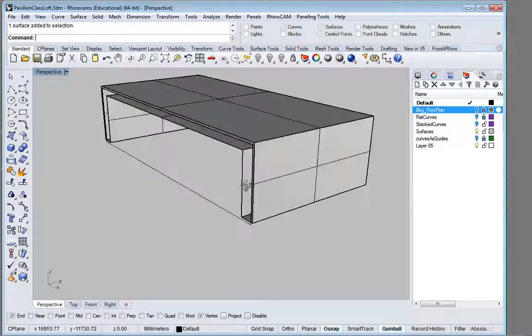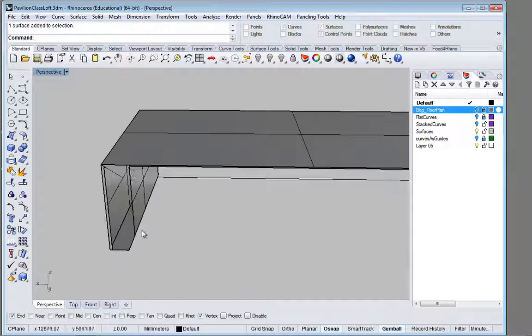The other way that I could do this too is that I could create that chamfered surface, which would require me making that kind of guide object anyway. So I could subtract that. But since I have to do that anyway, it doesn't make any sense to do it twice. So just do it and build that chamfer like we did on the previous, using these surfaces as the guide. Does that make sense? Okay.